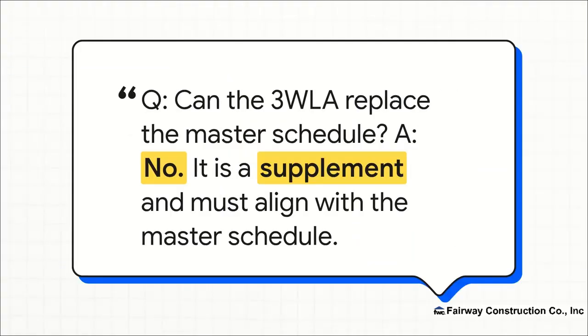Now let's be absolutely clear on this one, because it's a common question. Can the 3-week look-ahead just replace the master schedule? The answer is a hard no. It's a supplement, not a replacement. Think of it as the detailed, tactical, boots-on-the-ground plan. But it must align with the big picture, the master schedule that the project manager is managing.